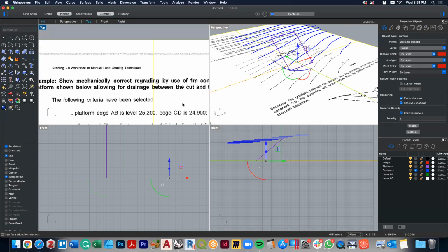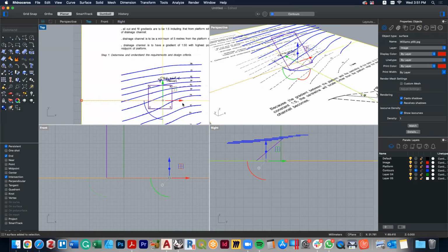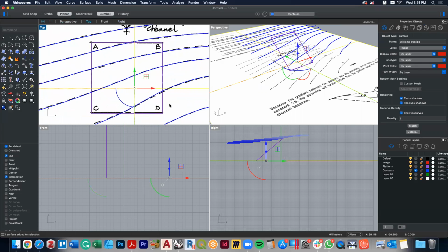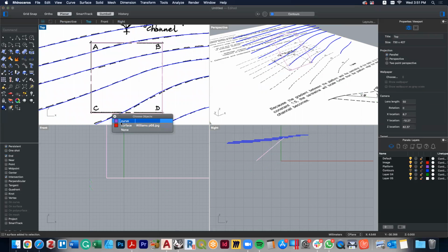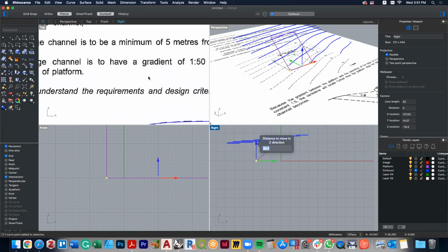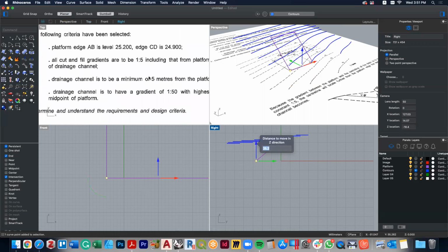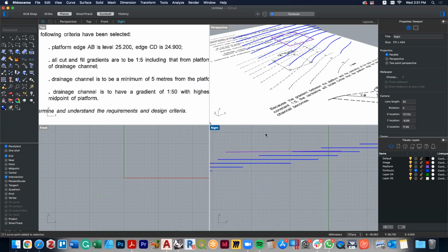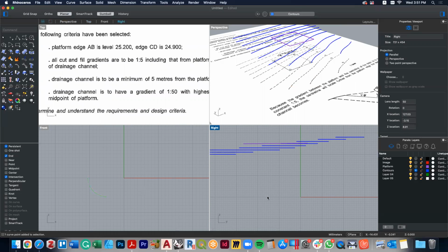And then you can see that at the bottom, I also have another one. So I then have to set the bottom. This is what's called a crossfall. So I go there, press shift again, go there, and then I'm clicking here. And what I'm doing now is choosing the other one, which is 24.9. So now you can see that that's actually a sloping platform, which is what we want.